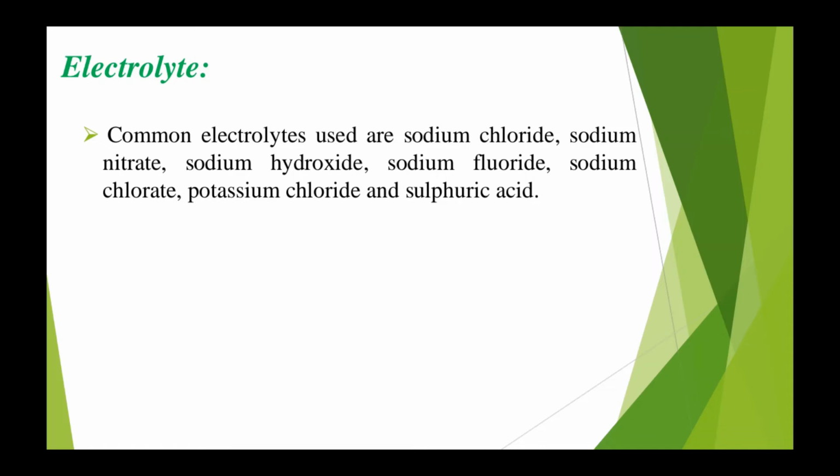Again, it dissipates heat produced in this operation. The essential characteristics of this electrolyte include good electrical conductivity, non-toxicity, and chemical stability. The electrolyte should have low viscosity and high specific heat. Normally, high velocity flow of the electrolyte over the surface is one of the key factors of electrochemical machining.